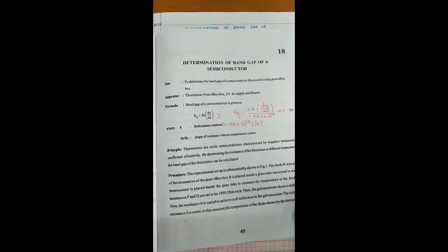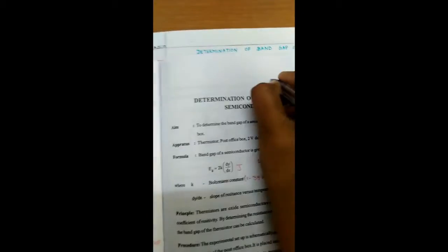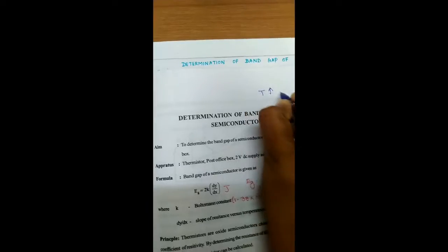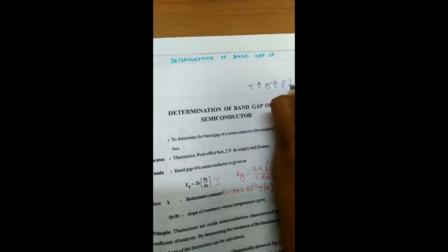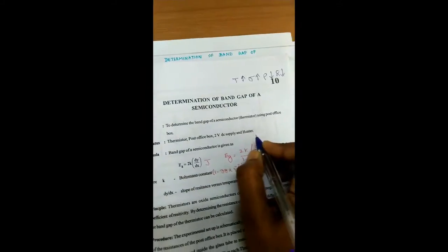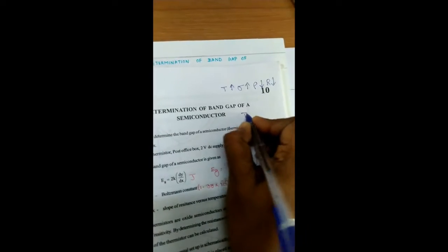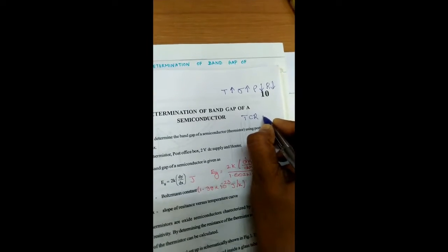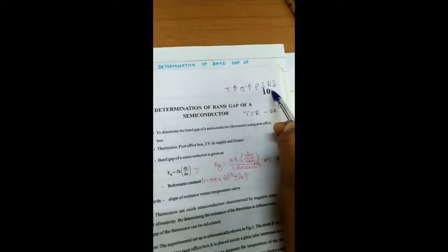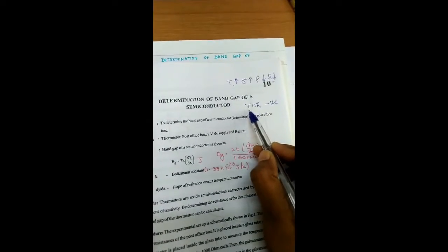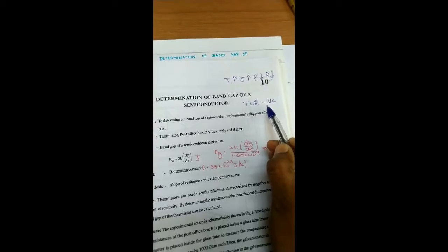And when the number of free electrons increases, the electrical conductivity of the semiconductor increases, and consequently the resistance and resistivity of the material decreases. That is, when you increase the temperature of a semiconducting material, the electrical conductivity increases, leading to the decrease in the resistivity or resistance of the semiconducting material, and hence we say the temperature coefficient of resistance of a semiconducting material is negative. That is, there is an opposite trend here. When you increase the temperature, the resistance decreases, and hence you say the temperature coefficient of resistance is negative for